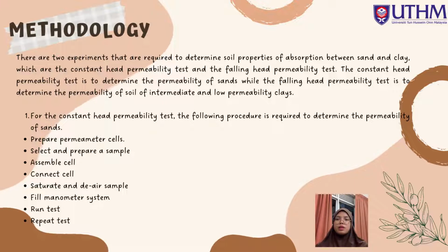Turn on the constant head device water supply, which should first be turned on at a low level. Empty the measuring cylinder before beginning a test run. Then set the timer to begin when the cylinder is positioned beneath the outlet overflow. Read the water levels in the manometer tubes and gauge the outlet reservoir water temperature. Repeat the test, empty the cylinder, and perform 4 to 6 more runs at intervals of roughly 5 minutes.